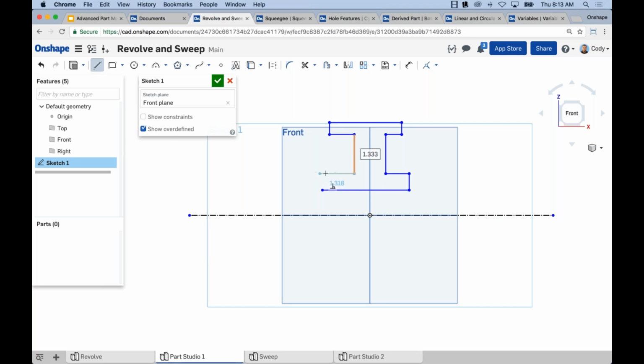Another good example, I want this line to end vertical of this bottom, the point below it. Again, move my cursor over the point, wake it up, move it back, and now I have that reference. The big thing there is, of course, I then don't have to go back and manually constrain things, right? I don't have to go in and manually add constraints. I'm just waking up those constraints as I'm sketching.